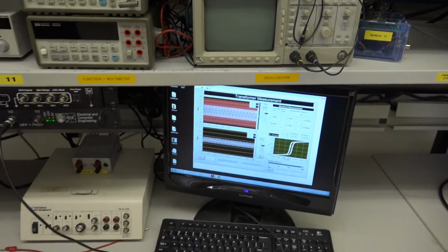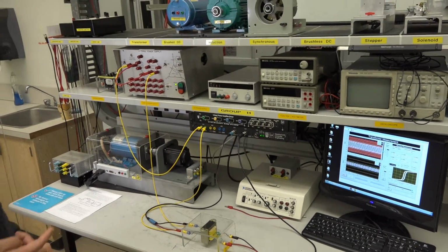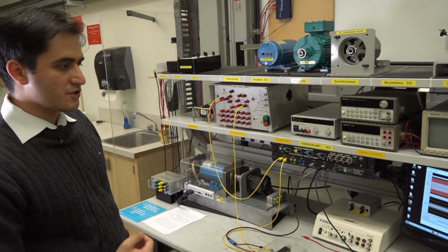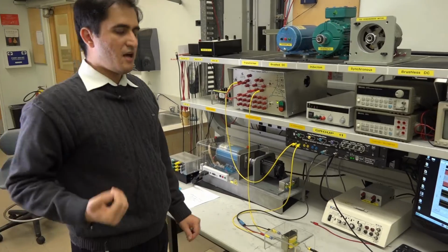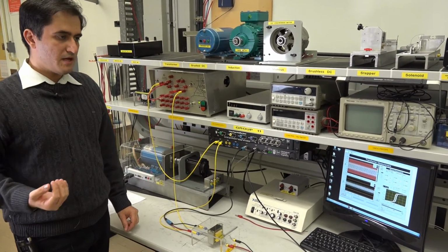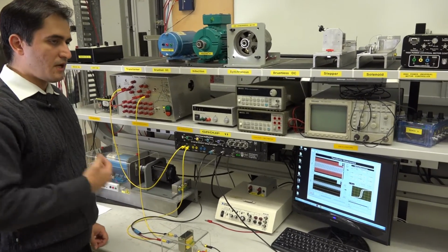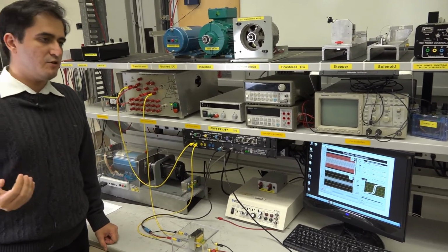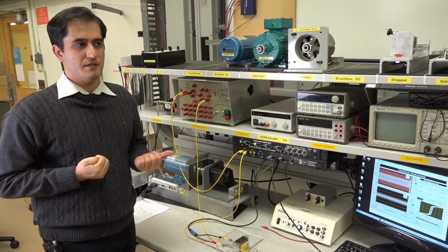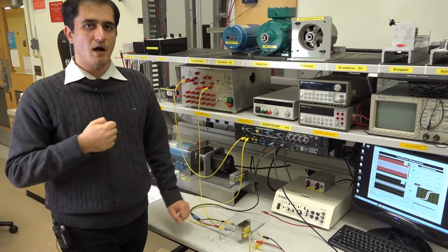You are going to do the inrush current test for two cases. One case when there is a high amount of inrush current when you connect the voltage, and another case when there is nearly no inrush current. And then you will compare the voltages at the moment of energizing the transformer, and you'll see the effect of the voltage at the moment of energizing on the inrush current.